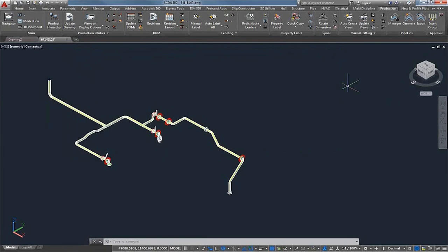You can also create files using the export command, and I'll explain a little bit of difference between the generate and export in a moment. When you hit the export command, it asks you to do 2 steps first before opening up the PipeLink Manager. First of all, it's asking you to select the objects you want to export. So in this case, you actually are making these decisions. It's not just going to be the entire, everything that's inside the drawing that you can see.